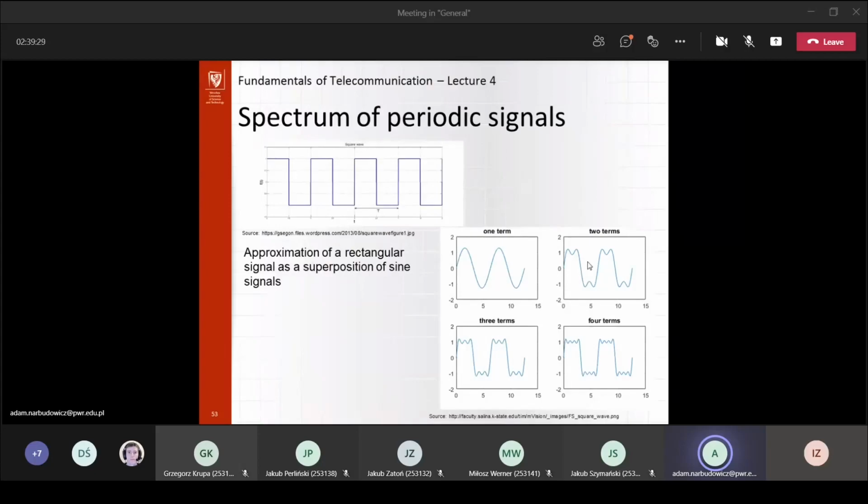when we move between time and frequency, and typically when we have the perfect rectangular filter in the frequency domain, the same principle but reversed is applied. So basically, we cannot have a perfect rectangular filter simply because it would require a signal which goes in time from minus infinity to plus infinity, right? And we simply usually cannot wait that long with our signal processing. Okay, so this is another reason why, when you use a low-pass filter, any type of filter, it will never be a perfect rectangular filter.